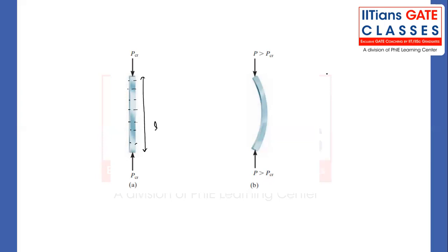This bending phenomenon is a very severe phenomenon, my dear friend, in the case of columns. Now you might be thinking, sir, we might have discussed bending in the beam also. Suppose this is the beam and we are applying some kind of load. Then what are the deformations and deflections you might have seen? So this was the elastic curve that we framed, and here we said that this particular deflection must be less than the permissible one, whatever the maximum deflection is, PL cube, or here W load divided by 48 EI. So whatever this value is, that has to be within a permissible limit.